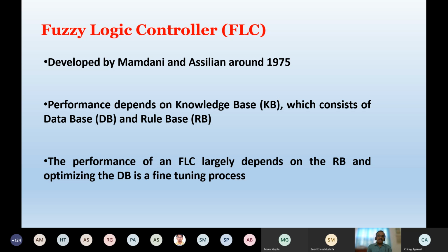Although this is called the fuzzy logic controller or fuzzy reasoning tool, once it has taken the decision, there is no fuzziness on the decision. It is called so because we use the concept of fuzzy sets to develop it. But the output of the fuzzy logic controller is crisp in nature. Please do not forget this fact.